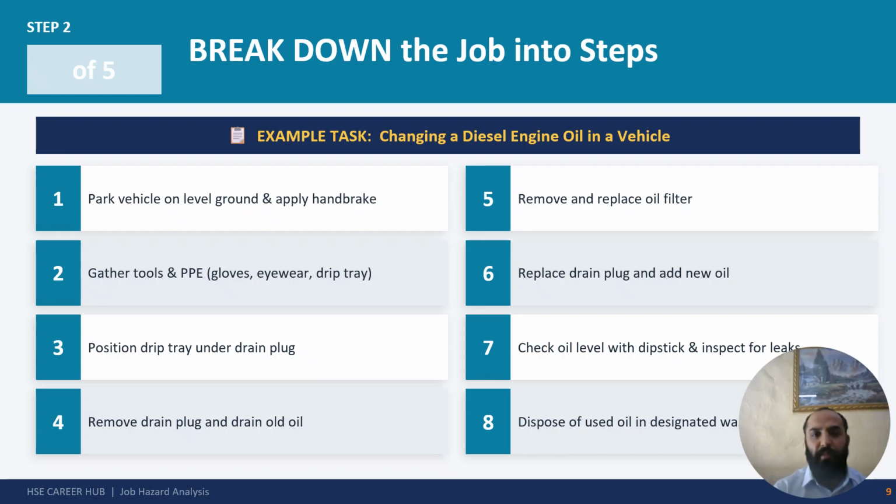Step 6, replace the drain plug, add the correct amount of fresh oil. Step 7, check the oil level with the dipstick, inspect for any leaks. Step 8, dispose of the used oil in the designated waste container. In this 8th step, we have a clear job specification of every step. 8 clear step, clean, logical.